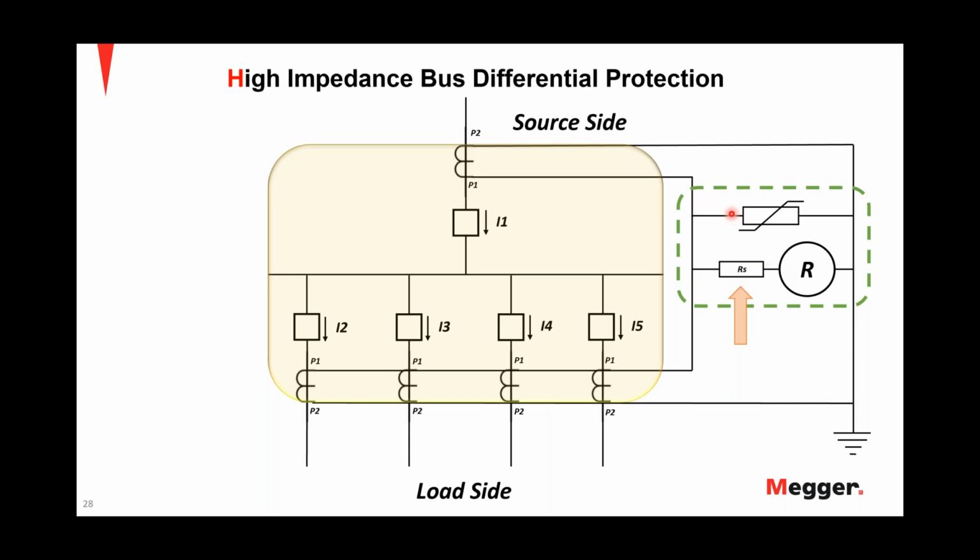And along with this, we have a varistor that is included across the measuring pad. I call this a measuring pad, because any differences that these two sides are seeing, that current can be forced through this pad. And we have this varistor across this pad so that it can protect the relay and CTs from being damaged due to high voltages. You can see that this point is grounded so that it prevents harmful voltages appearing across the circuit.